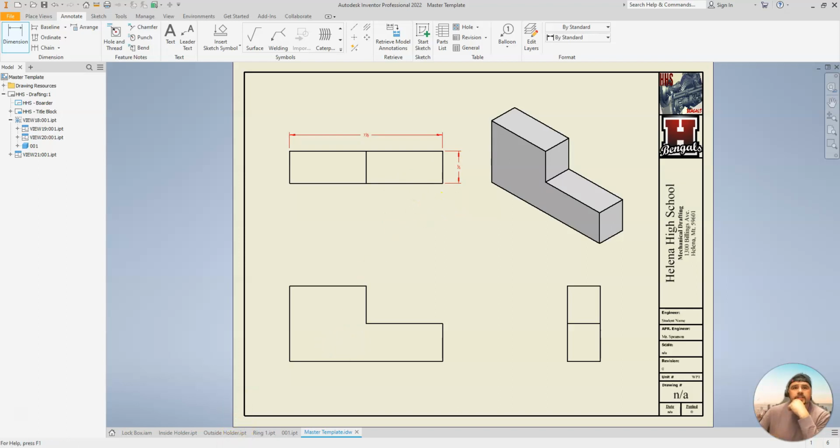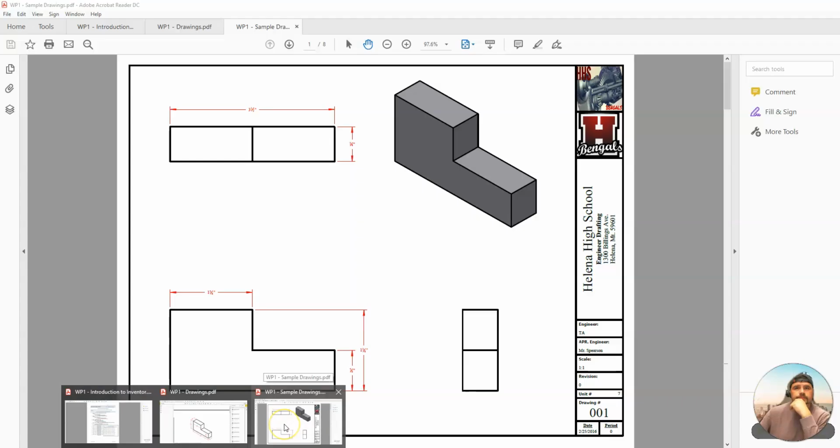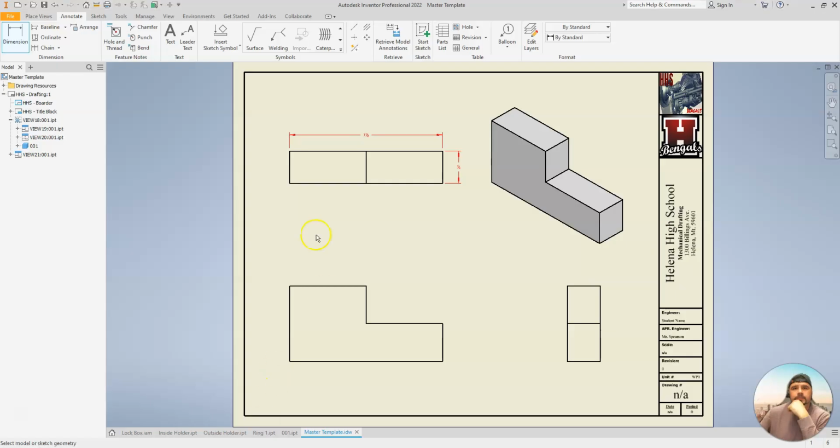Okay, we're going to continue on with this. I'm going to do these last 3. I'm memorizing them. Boom, here we go. I'm still in dimensions. I'm going to select it. Notice when I dimension this, I'm not selecting point to point. I'm selecting the line. But you will notice that when I select this point, and notice when I scroll out, it snaps for it. I've already set up all of your templates on how they need to snap. So I could continue dragging this, and it'll keep snapping in the increments that I set it up for.